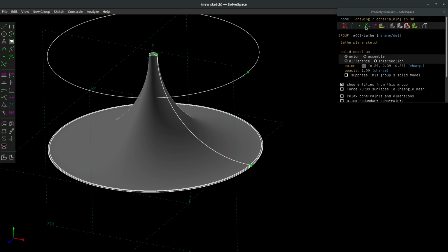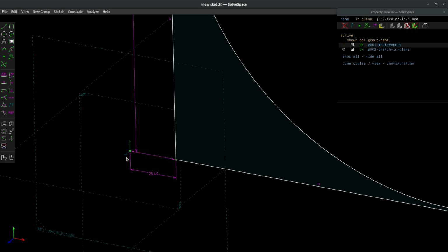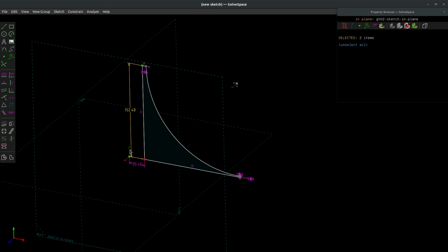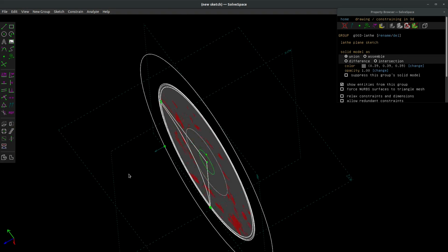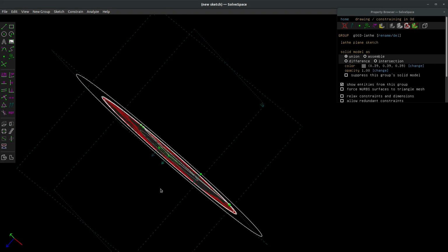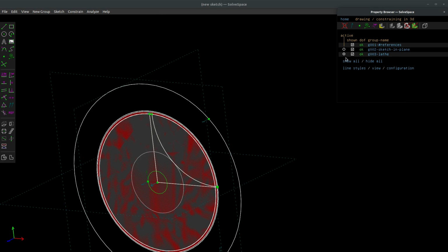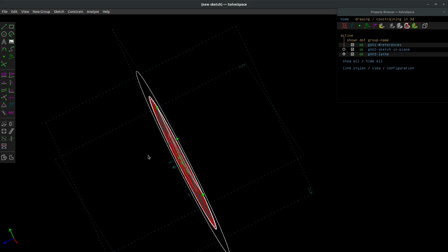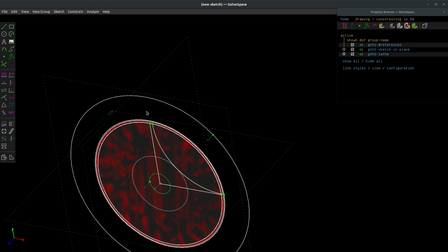Similarly, hopefully this may clear up any questions that anybody might have. I can revolve this orientation on this point, and we would be revolving off of this invisible line that I just moved my mouse down. When we revolve, you can tell there it's an infinitely thin revolution that isn't valid. If we go home, you can see we've just created an erroneous surface. It's not good.